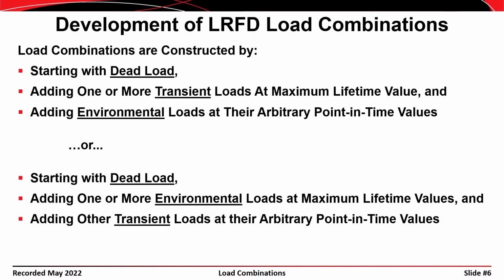But it isn't really rational to design for the maximum live load that the building's ever going to see at the same time that you have the maximum snow load that the building is ever going to see. Odds are, if it's a 50-year snow event, that most of the people that would otherwise occupy the building probably won't be there. So that is the basic approach that goes into the development of these load combinations.